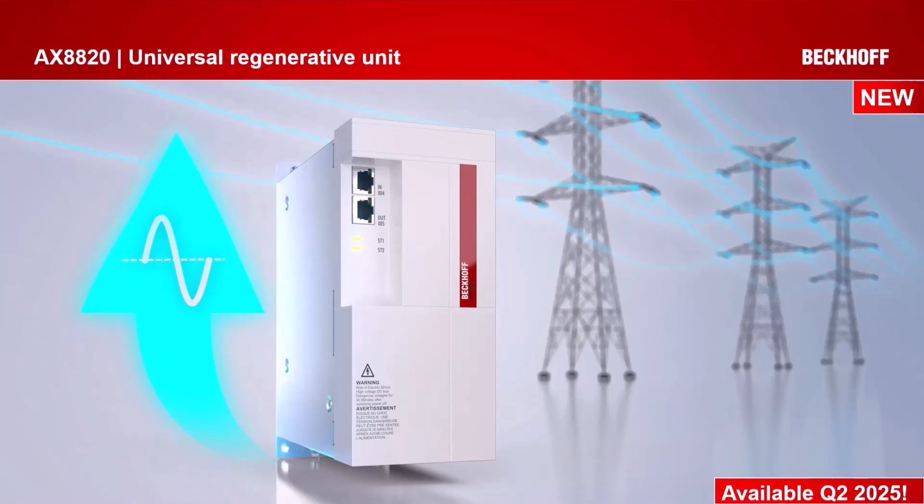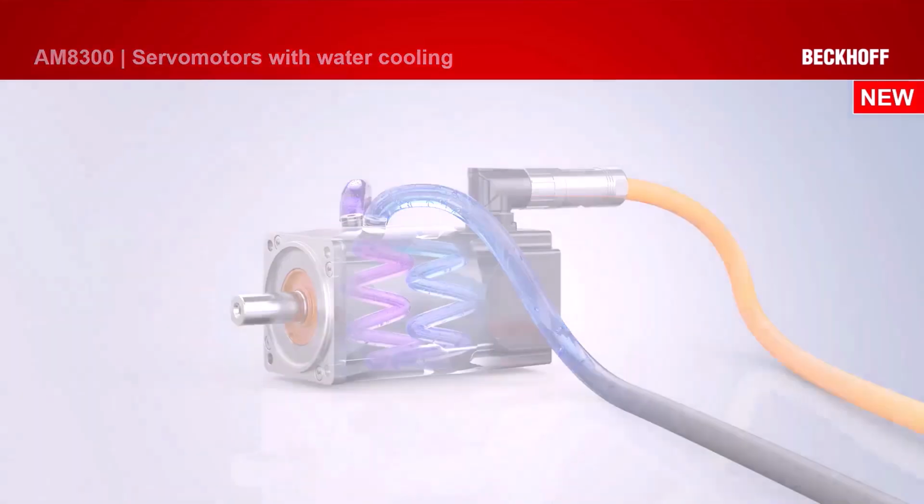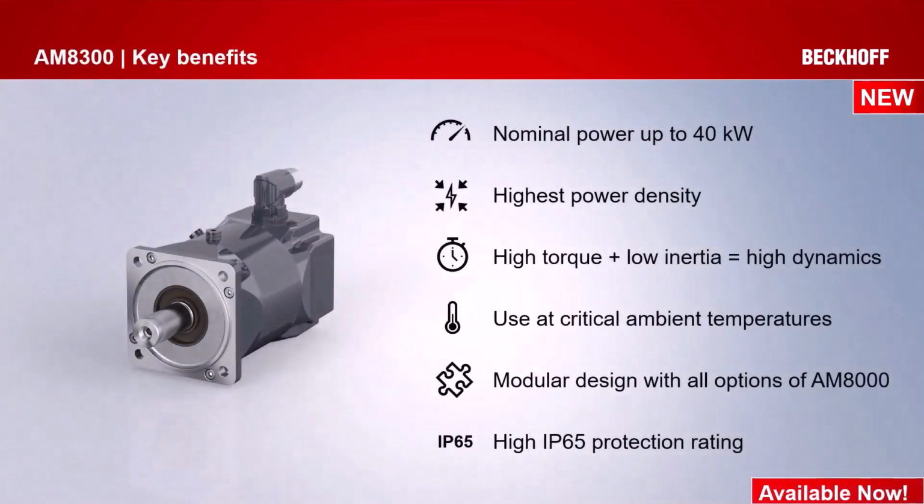This is a way you can take your regenerative power and put it back on the mains grid to help make your machine more power efficient. Our water-cooled motor is available now, and this will give you 40 kilowatts of power, very high power density, so that's the nominal output power. So all the way up to 240 Newton meters worth of torque, high dynamic application.